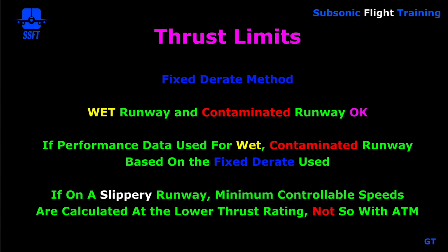If you're on a slippery runway, the minimum control speeds are calculated at the lower thrust setting. And again, not so with the ATM method, which is why there's no guarantee that you can maintain controllability on a contaminated or slippery runway.